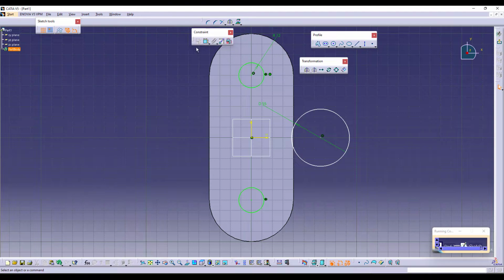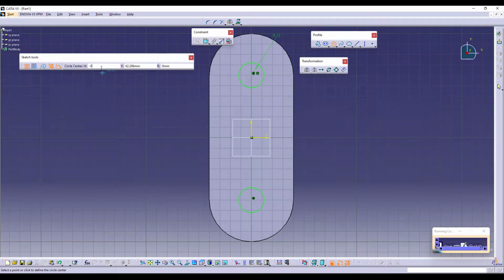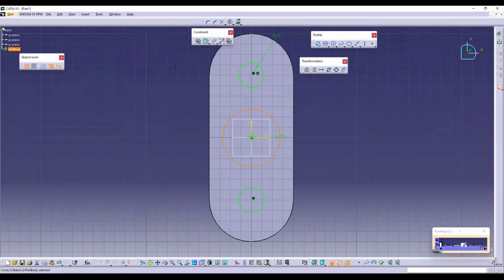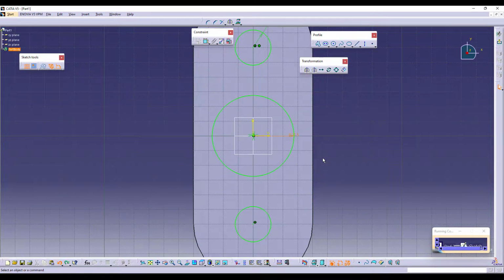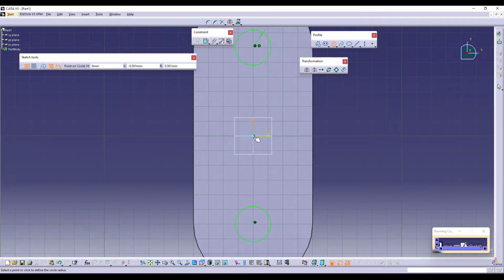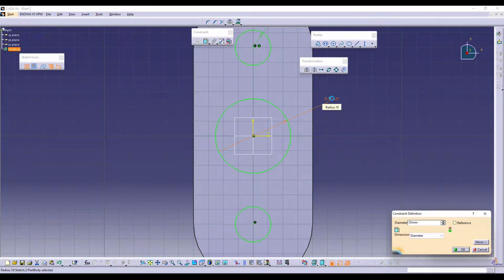You can actually use any feature or any option while making this whole circle. For instance, if you do not want to make it this way, for example, I have actually taken a circle. I can just select the circle and start giving my coordinates as well. If I know the center is 0 and H comma V is 0 and the radius, which is actually 22 point, sorry, it gives you that particular circle as well, 27.5. It's up to you, you can do this as well, or you can directly take a circle and make it exactly at the center, which is 0, 0 and then start dimensioning it. Whichever you feel flexible while using the software can be done.